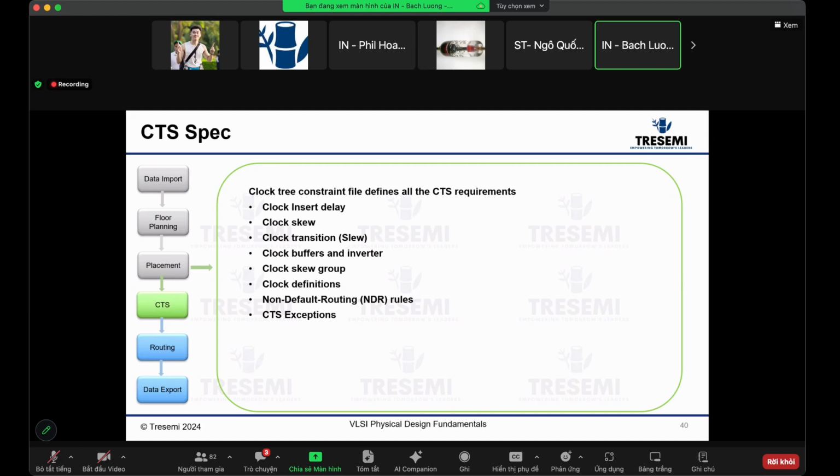Okay, so what's the setback? What is the negative or disadvantage of using wider metal? Those are correct. What's the reason? What's the setback? What is the negative impact if we use wider routes for the clock nets? More area, it takes up more tracks. That takes up more routing resource. That's true.